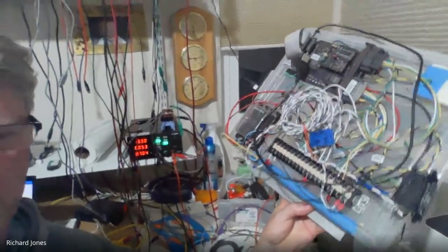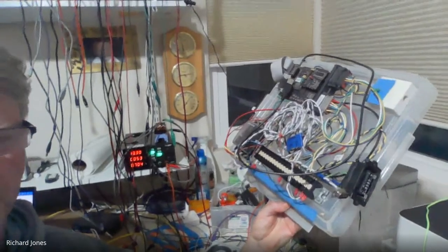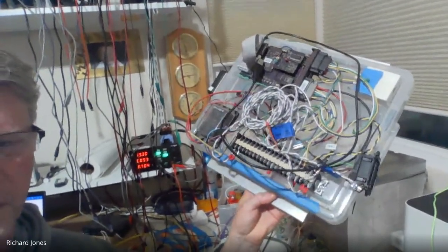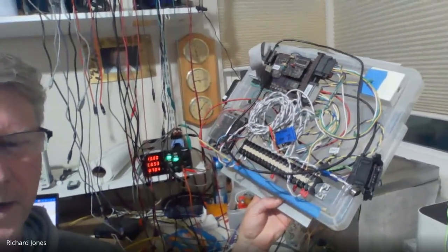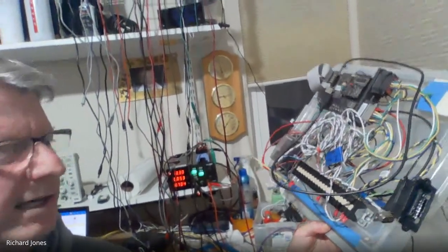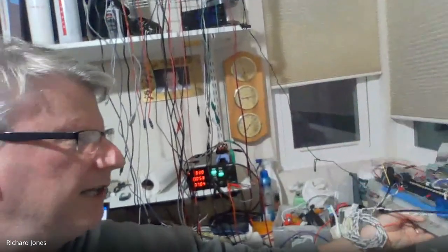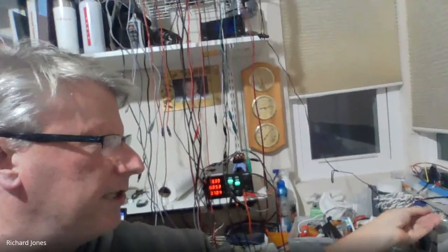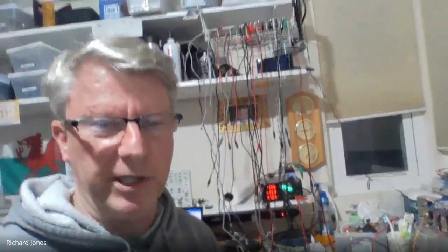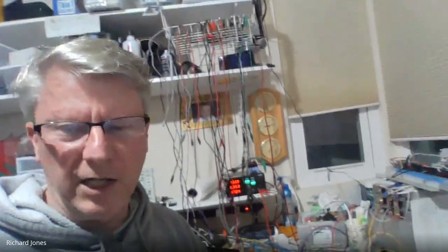This is rather cool. This horrible looking janky box is the VCU that came out of my son's S10 and later his Doka. It was the same box that did everything. And on here, there are actually two CAN buses on this particular bit of hardware, because I had a device that was 250K, a power distribution unit to power up everything, which was very convenient. And then everything else was 500.